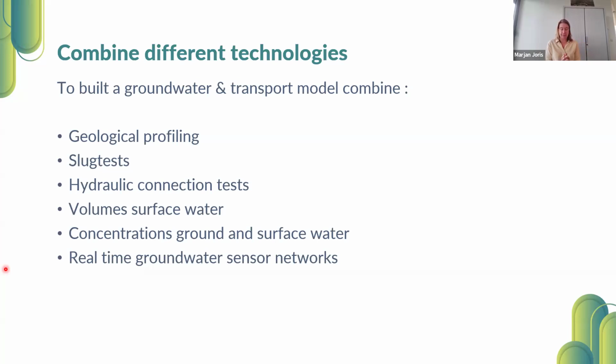Indeed, fractured bedrock is not an ideal soil for measuring with iFlux samplers, because the flow will be dominated by the fractures, and we measure in existing wells, and if you drill a hole in the bedrock, there will be new preferential pathways initiated by the drilling works, for example.